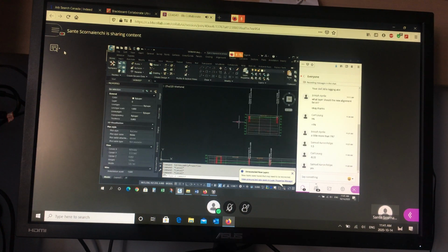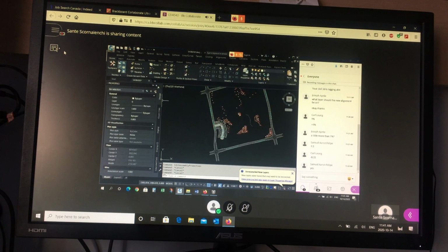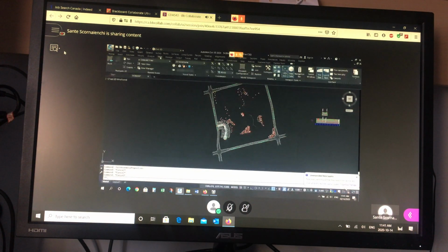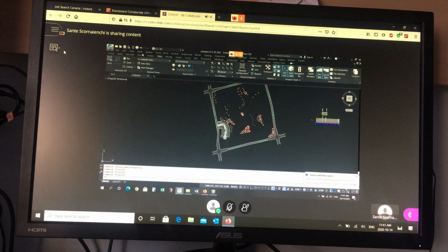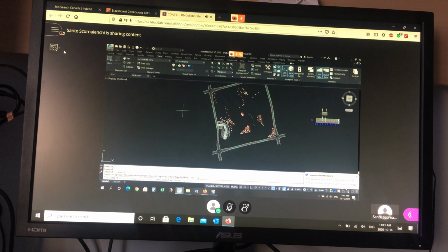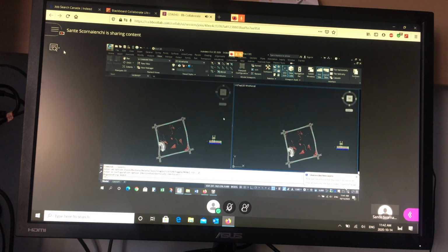So in the corridor, I'm going to change my screen view. I'm going to split my screen. Don't do this, this is just for demonstration purposes. I'm going to go to View, then Viewports, then 2 Viewports, and I want to split it vertical. I'm actually going to split my model space into 2 parts. This is not paper space, this is all model space. So now I have 2 views of the same thing. Don't do this, I'm just doing this so you can see what happens.